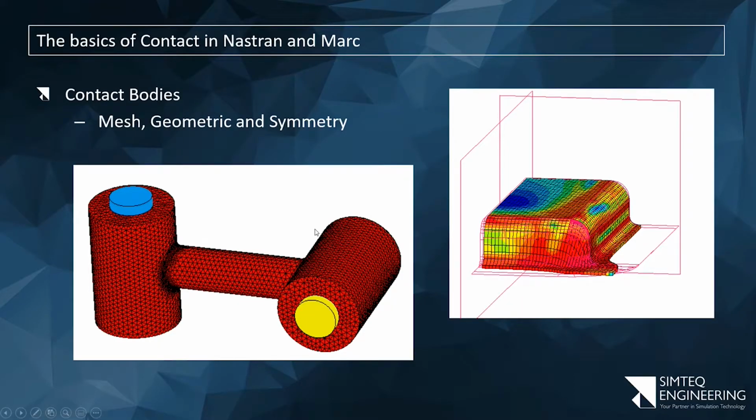Okay, then if you look at contact, how do I define what can make contact to something else? In Marc, we define that by using a contact body. Sorry, when I say Marc, it's Marc and Nastran both. So we can define three basic types of contact body. A mesh as a contact body, geometry, which is a surface or a curve, depending on whether it's a three-dimensional analysis or a planar axisymmetry or plane stress, plane strain analysis. And the last one is a symmetry type.